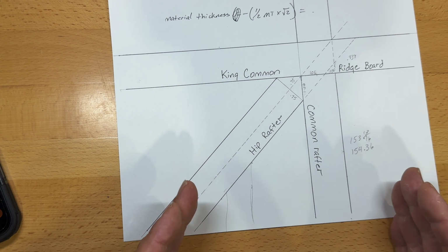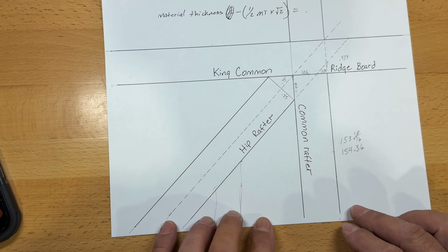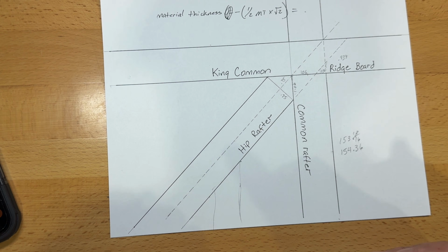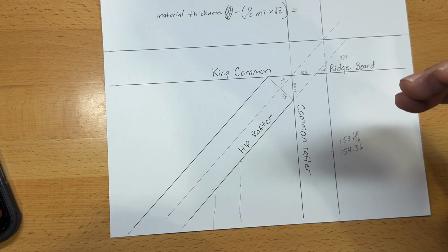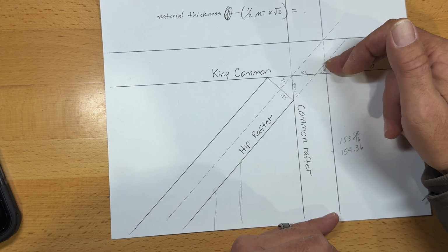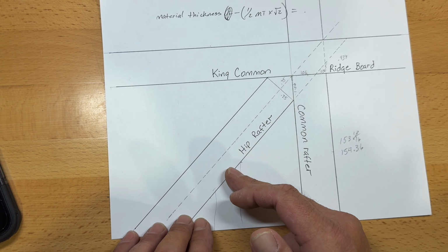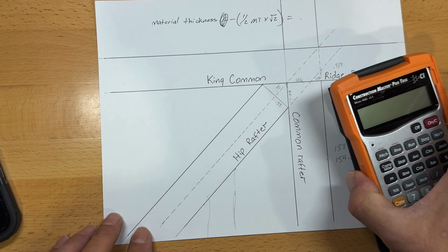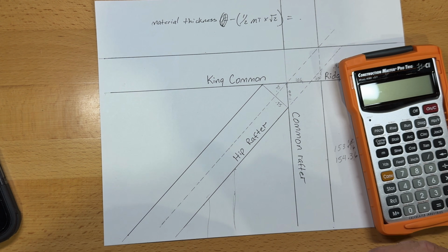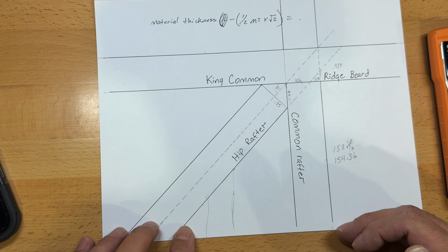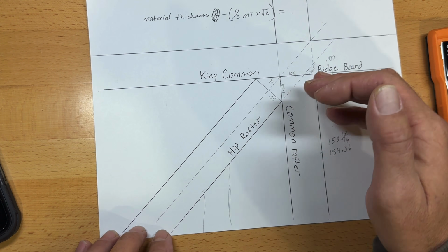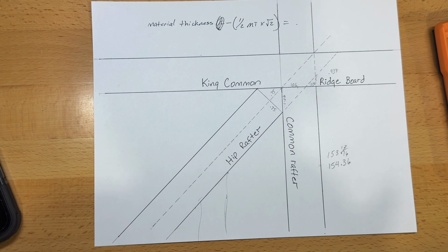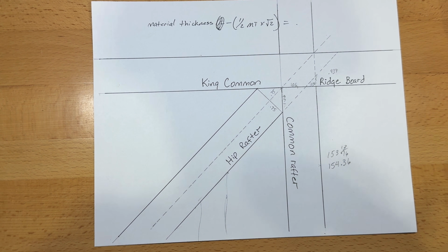But for standard lumber, whenever you want to get the jack rafter placements correct, this is the best way to do it, so that you can very easily, it just adds to it. It's going to place the jack rafter in the right spot, and then the placement between jack rafters, it calculates correctly. So that's not an issue. You just need to add 0.439 to the length of your run in order to make your jack rafters come out correctly. I hope this helps for those that are in roof construction or roof framing.